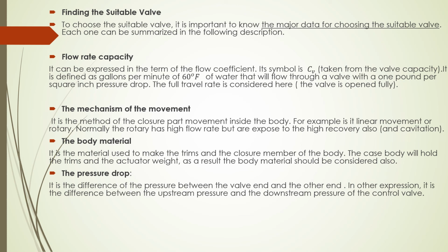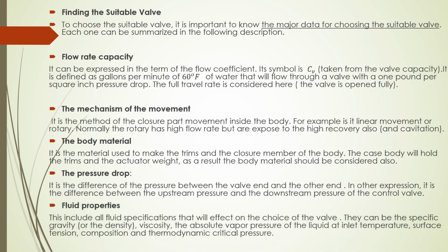Finally, the fluid properties that include all fluid specifications that will affect the choice of the valve. They can be specific gravity or density, viscosity, the absolute vapor pressure of the liquid at inlet temperature, surface tension, composition, and thermodynamic critical pressure.